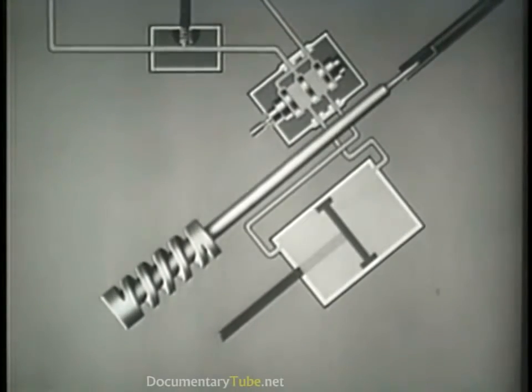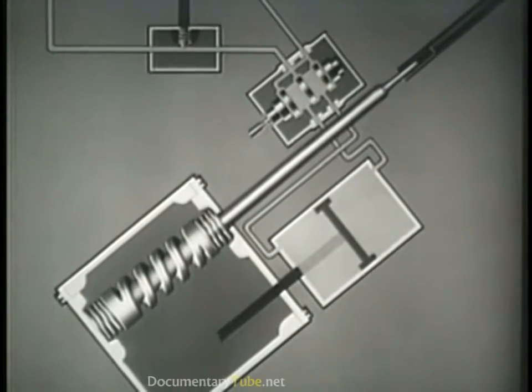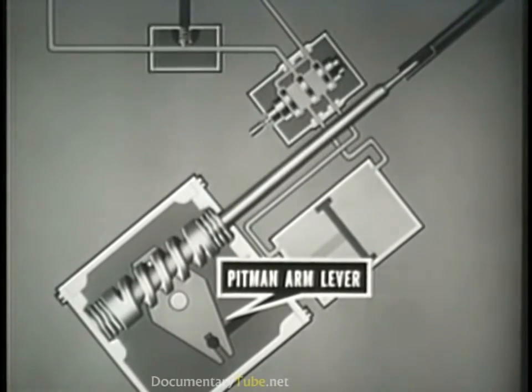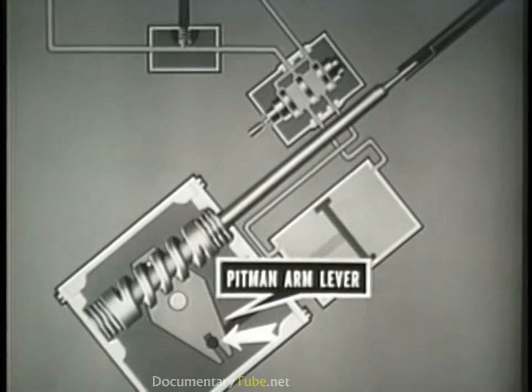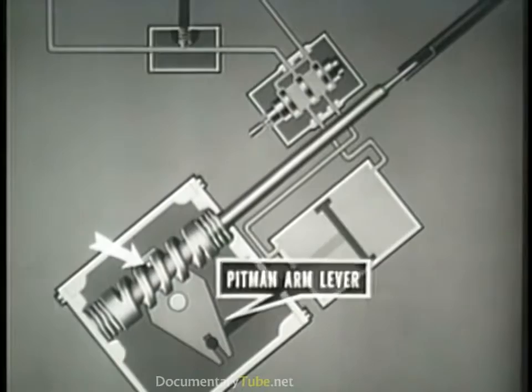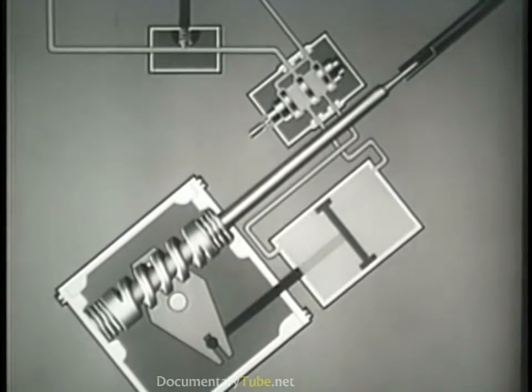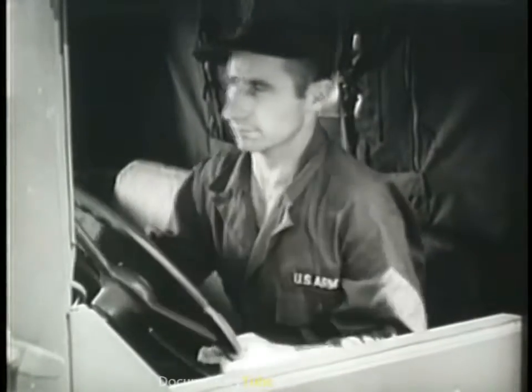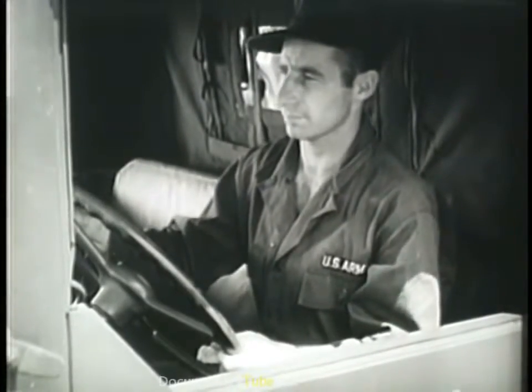The cam is held in center or neutral position by a spring at each end, supported by the steering gear housing. The pitman arm lever, which actuates the pitman arm, has one end fastened to the piston rod, the other in mesh with a groove in the steering cam. When the steering shaft is turned, it requires a greater effort to turn the pitman arm shaft and lever than to compress the springs at either end of the cam. This is so because the pitman arm shaft and lever are connected to the front wheels.